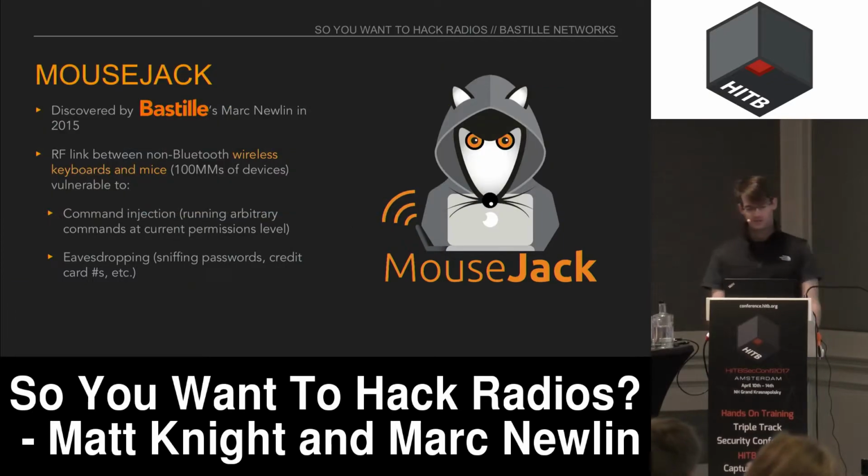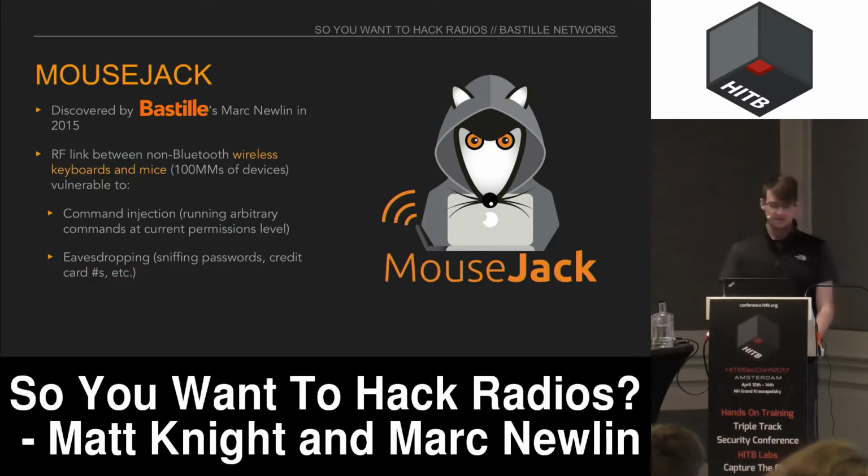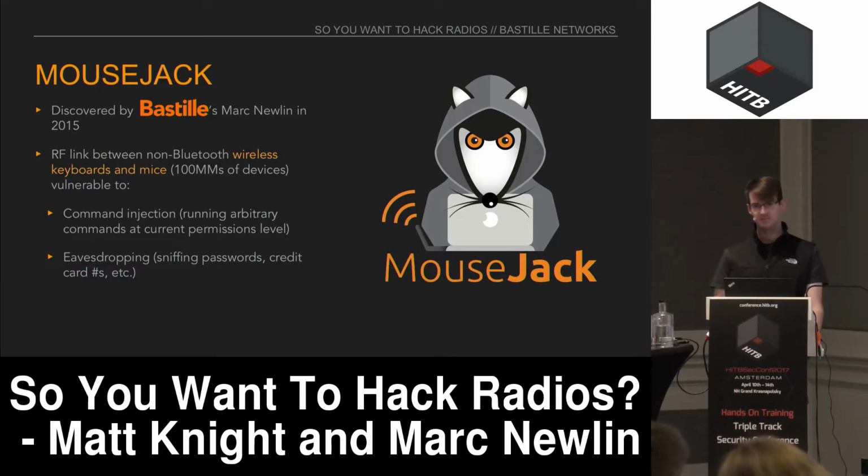The second vulnerability I'll talk about briefly is the MouseJack vulnerability that Marc discovered in 2015. And Marc analyzed the RF link that connects non-Bluetooth wireless mice and keyboards to the dongles which you plug into the computer. Now, I say non-Bluetooth because they use a PHY that's made by a company called Nordic Semiconductor. The physical layer is very similar to Bluetooth, but it doesn't have any of the MAC layer networking or security protections on top. As a result, it has better battery life and is less expensive, but obviously you don't have those features built into the protocol. It's left up to the manufacturer to implement those things on top.